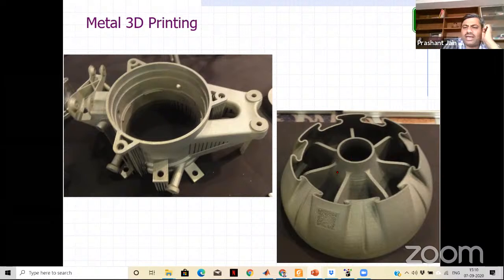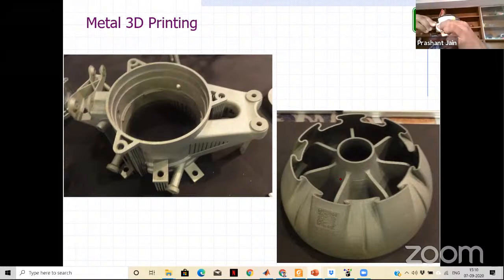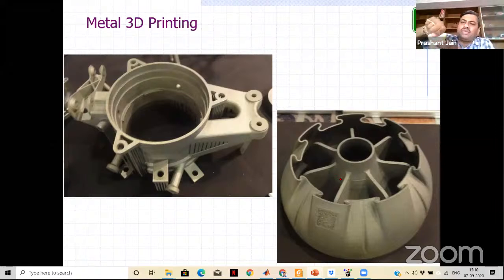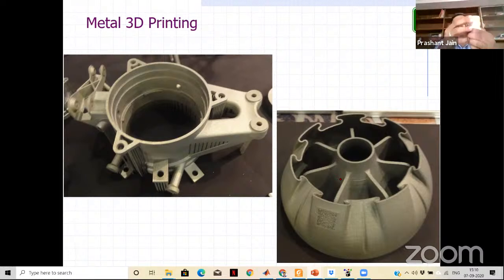Right? You can have a pattern, and then if you apply the casting, that casting should be opened to remove this part, right? Say if I have this cup again, the handle is there here. I can have the casting of this part in two components, right? So I can have a parting line from here and this cup, right? Based on this parting line, I can divide this cup and cut the section in two parts, like this. So one part will open in this way, another part opens in this way, and this part will come out of the casting.